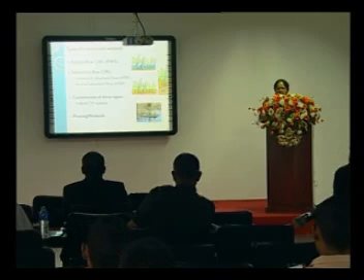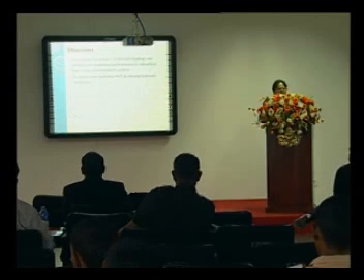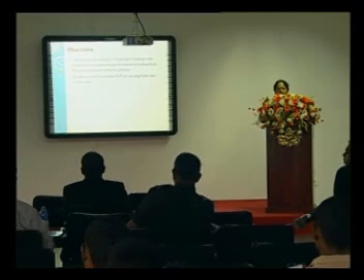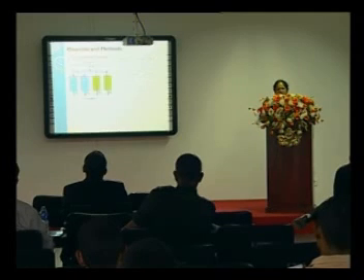In this study, we have studied horizontal subsurface flow and vertical subsurface flow constructed wetlands. Our objectives were to examine the impact of hydraulic loading rate variation on treatment performance in subsurface flow constructed wetland systems in order to reduce the land area requirement, and to select the most favorable hydraulic loading rate at varying hydraulic conditions.